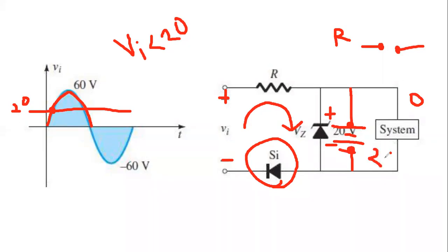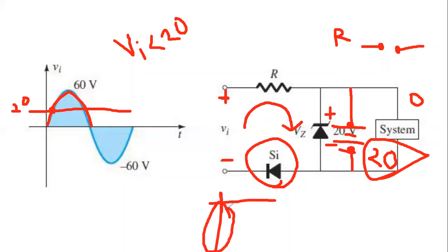This is the significance of giving a Zener diode, because when the input voltage crosses the 20 volt, at that time the Zener diode will transfer from the open circuit to the voltage source, because at that time the breakdown happens. If you remember the diagram, this is the breakdown region. The Zener diode enters into the Zener region. That is the significance of the Zener diode. I think you are clear.